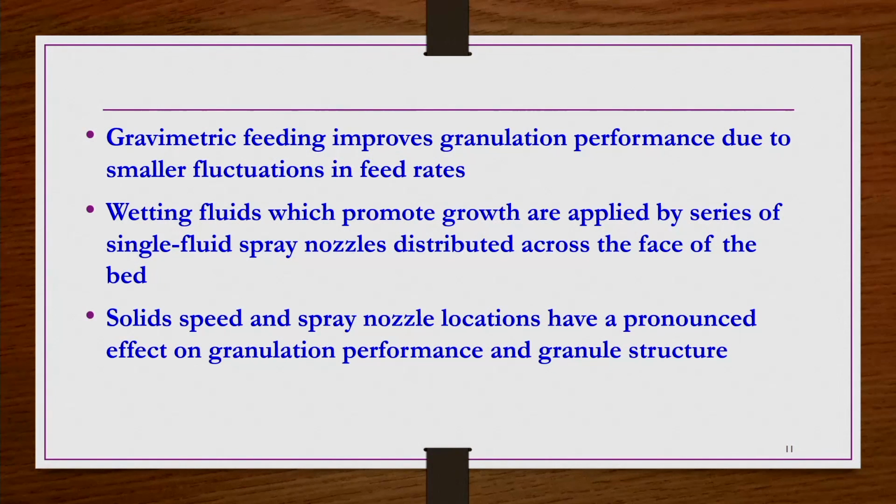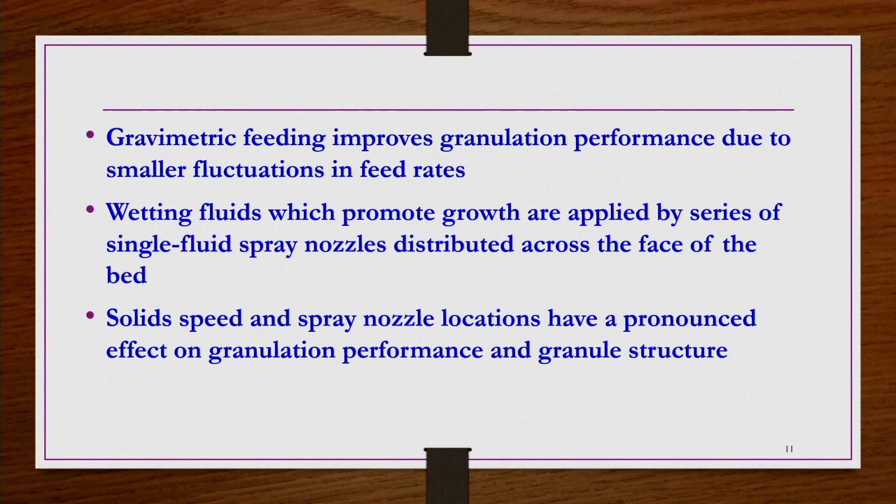are going to have a significant, pronounced effect on granulation performance and granule structure, because the feed should not be coming at a very slow rate, so that a large amount of binder solution is coming, and then when they are mixing, a kind of slurry is forming rather than granulation taking place. So, that should not be there. Similarly, solids should not come in at a very fast rate, otherwise without being granulated the particles may be leaving the container. And then the spray nozzle location also should be such that most of the spray is coming into contact with the incoming feed materials to the maximum possible level.